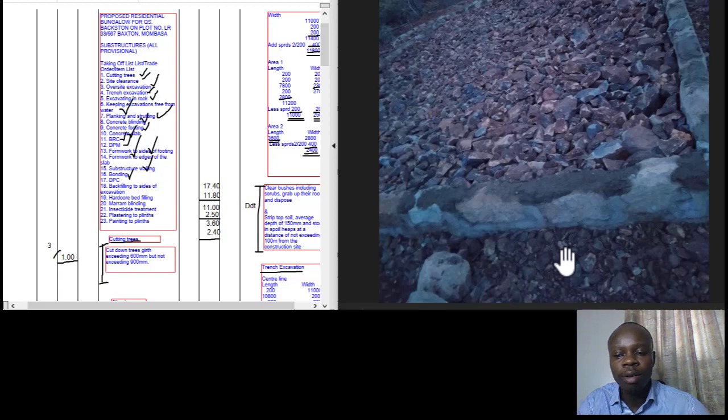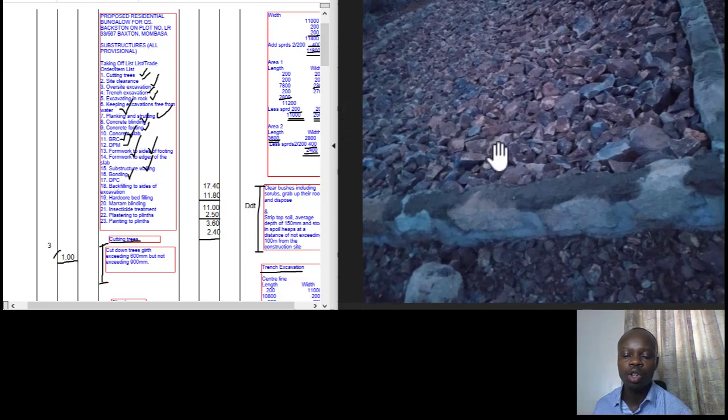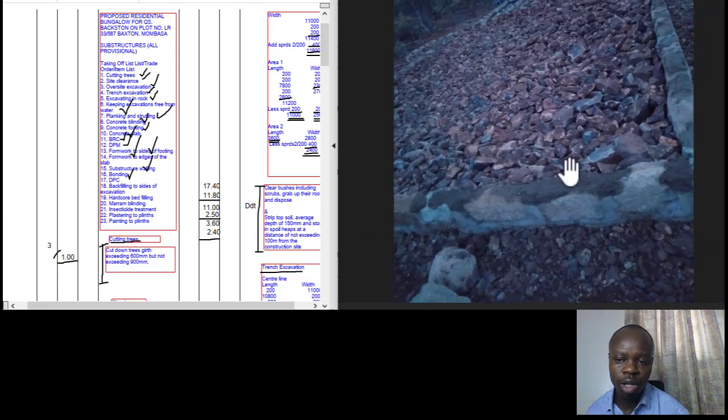But if, let me say, it's black cotton soil, then definitely you won't use it, because there's a possibility it's going to compromise the strength of your walling in one way or another, because it soaks water, or it allows much water, which is possibly going to weaken the masonry foundation wall.